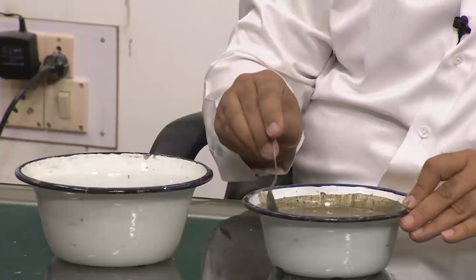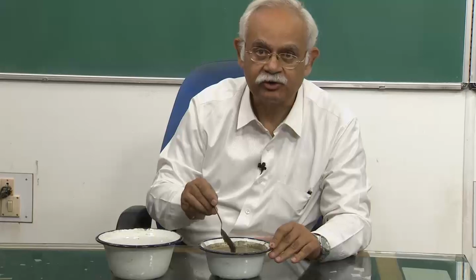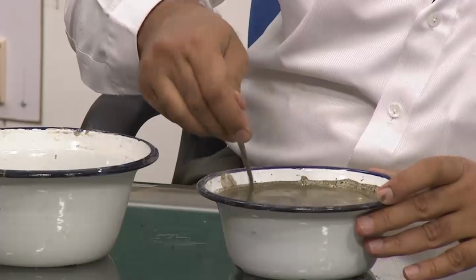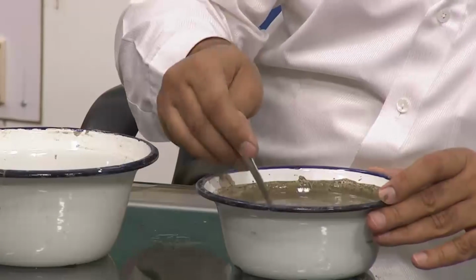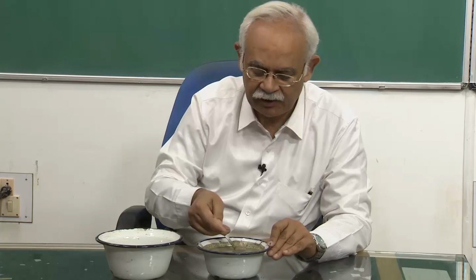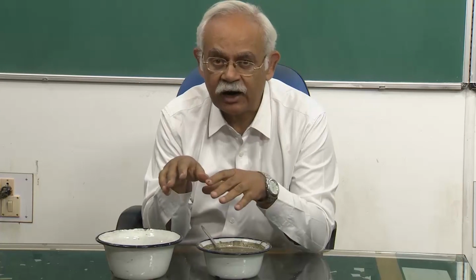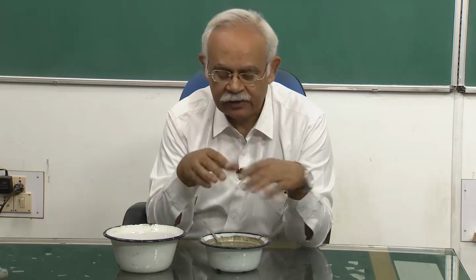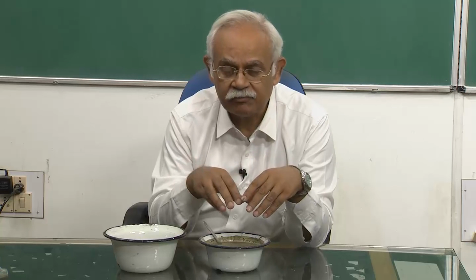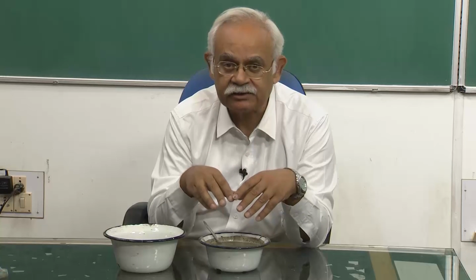Another thing that is very interesting to observe is that this mortar is highly prone to segregation. That is, the sand very quickly settles in the paste and the paste remains on the top and the sand settles down. So we have to be careful when we add plasticizers and chemical admixtures that there is no undesirable side effect. This is exactly segregation. Chemical admixtures making the mortar more susceptible to segregation, except of course we must remember that it is mortar.